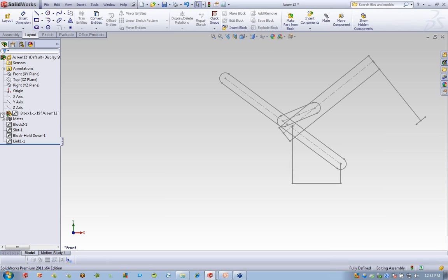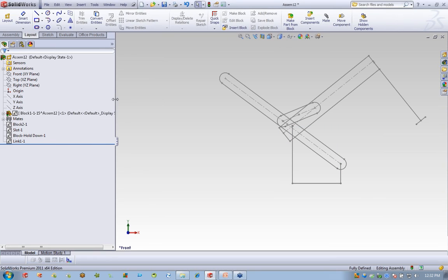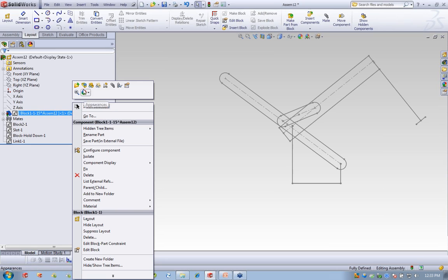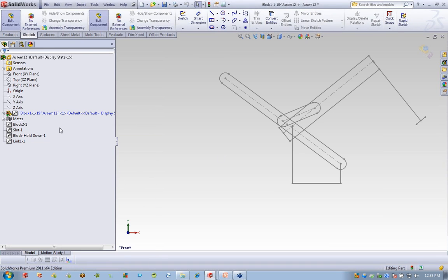Now what it does, it creates that part inside the assembly, and I want you to notice that it is a virtual component. You should be used to virtual components at this point. Those are components that only exist inside of the assembly. The way I tell that is with the brackets. So at this point, with the part in the assembly, I can do what I traditionally do, top-down design. I can edit the part.